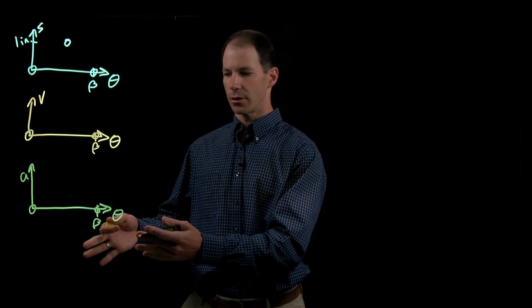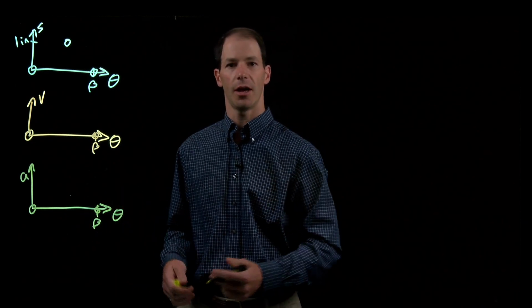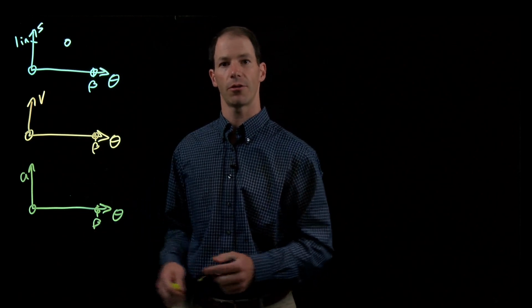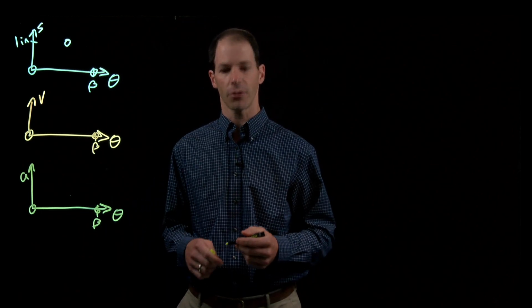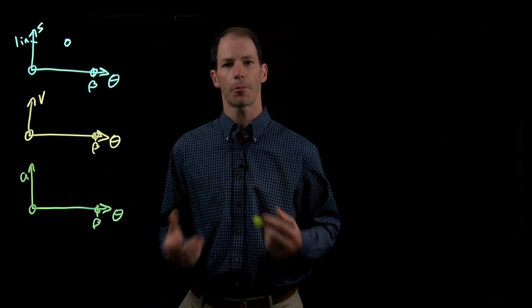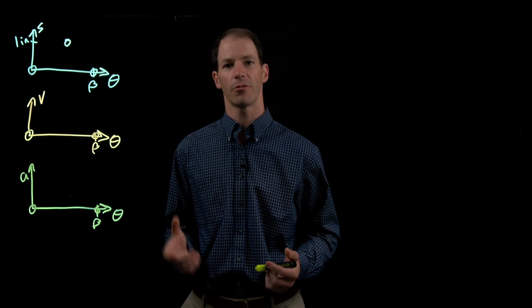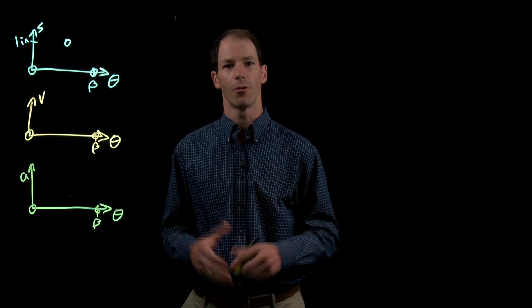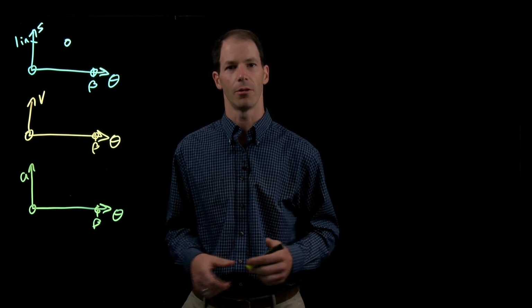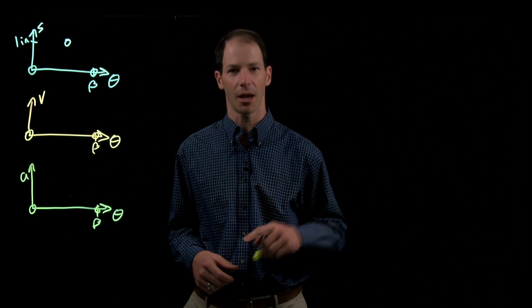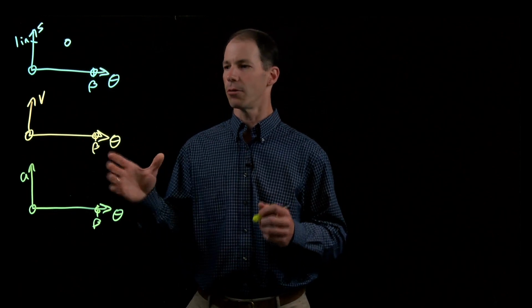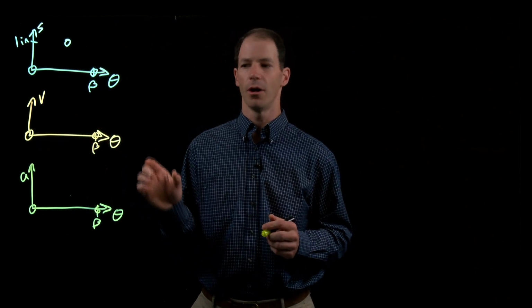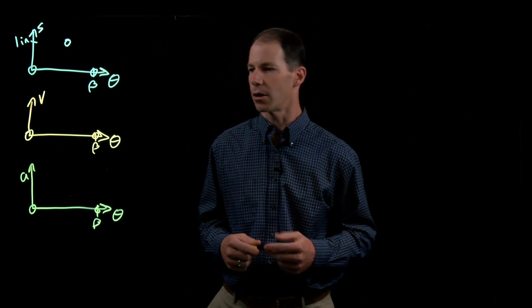Now we could also create another plot here for the jerk, and I could constrain the jerk to be 0 at the two ends as well, but we're going to find that gives us a much higher order polynomial. And the problem with having a high order polynomial is we get a lot of numerical oscillation in the profile, which can cause problems that we really don't want to have in a cam, oscillating back and forth.